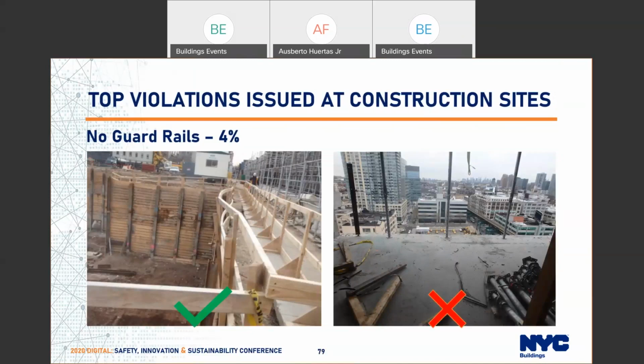On the left, we can see an excavation that has supportive excavation and guardrails. The guardrails are built appropriately with top and mid rails and toe boards. On the right, there is a leading edge with no guardrails, and no controlled access zone is established.